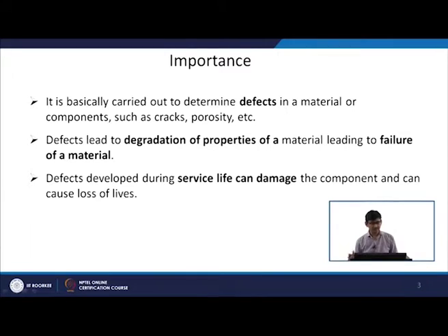Because they will degrade the properties of a material, and it may lead to failure of the material. If that defect is of a critical size and under the given stress condition in which this component is going to be used, this crack can start propagating. So, I want to see whether this crack is of critical dimension or much lower than that. Defects developed during service life can damage the component and can cause loss of lives. So, NDT is not only for components which are going out of industry, as a quality control tool.